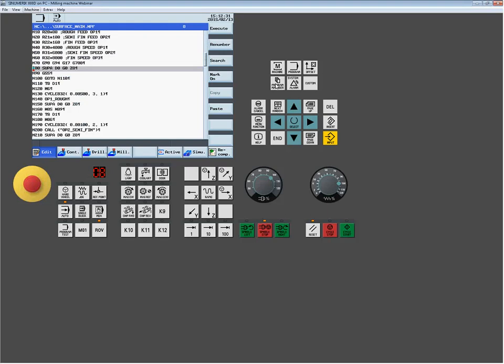That's what the D0 statement does. Puts it into a rapid mode and tells the machine to go away. Any of this stuff, if you're not familiar with it, I certainly recommend you go back to my earlier 808D milling webinar I did a few months back. We go through all these commands in a lot more detail because we actually write a live exercise.